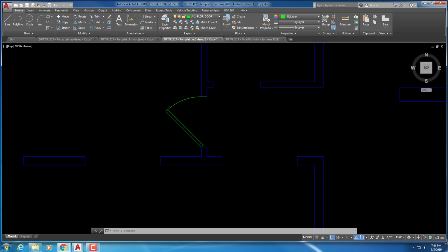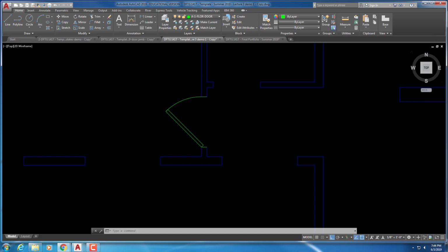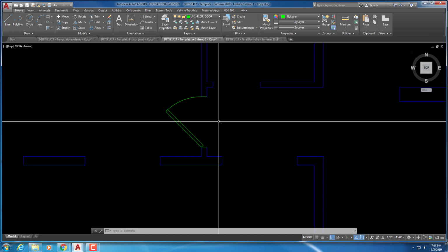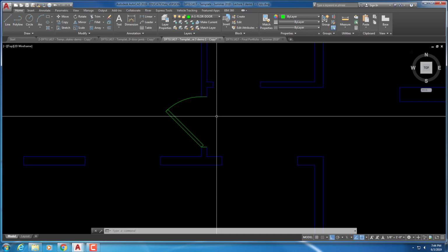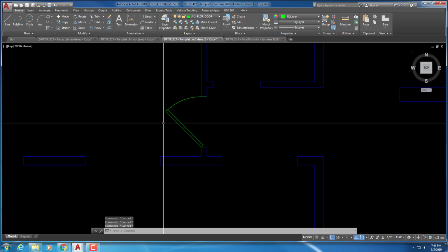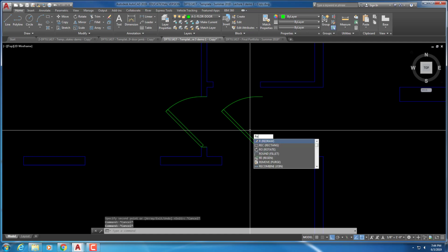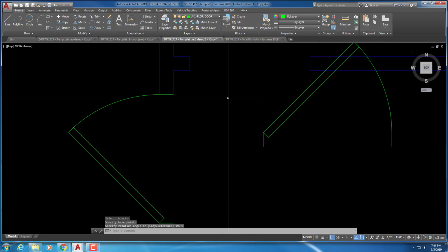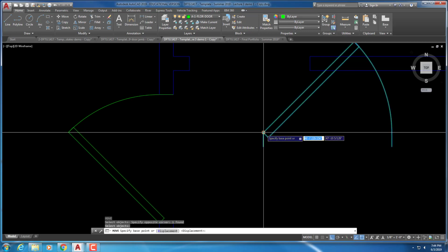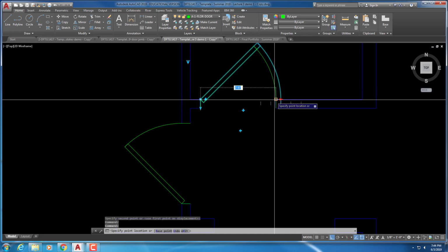The next door up is into the powder, which is a D3 door. The D3 is actually 2.6. Again, if you actually cut these openings the width they need to be, you can kind of just look at the floor plan to figure out which direction they need to go. So you could either bring in another door, or you could just copy this door and change it. Again, I think it's sometimes just easier. Maybe copy what's already there and then rotate it and then move it into place. This door is going to be 2 inches too big, so just move it back over this way.